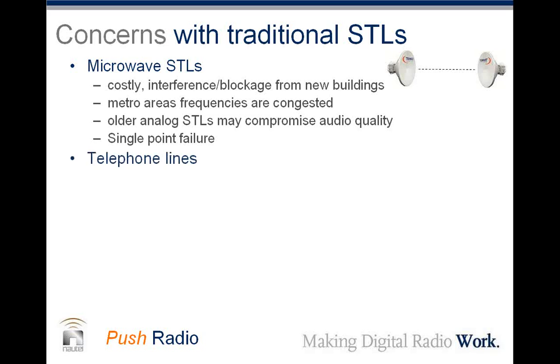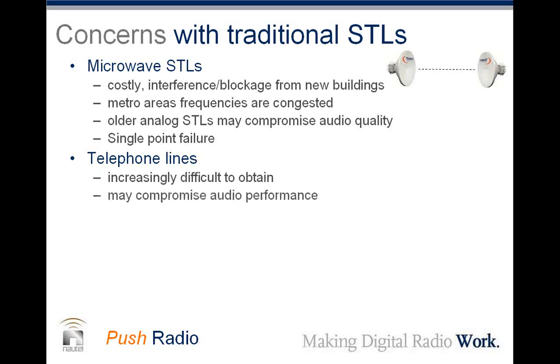Telephone lines, many stations have used telephone lines as an STL. They're increasingly difficult to obtain. I was reading some of the engineering blogs online, and people were talking about trying to negotiate with the telephone company to put in new copper pairs, which is very difficult to do in many parts of the world these days. They are also capable of compromising audio performance.